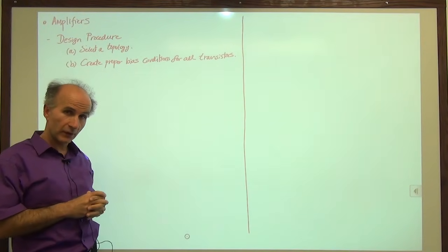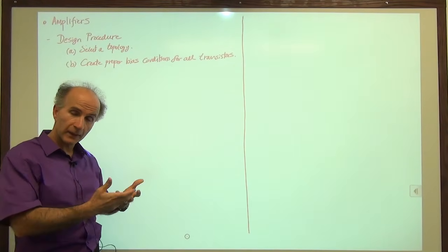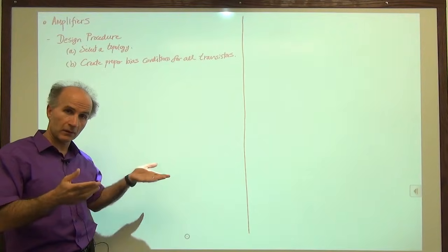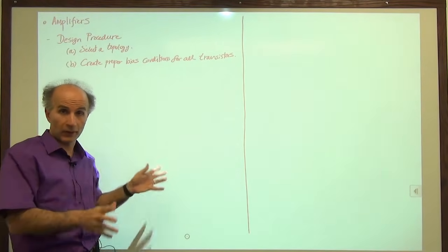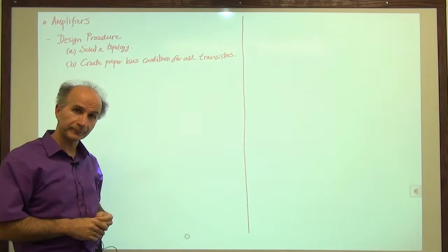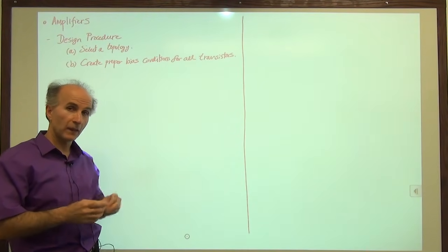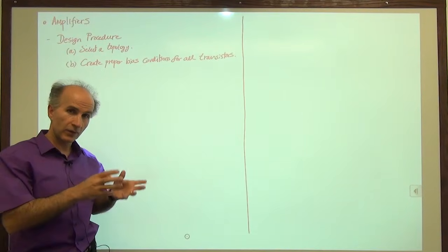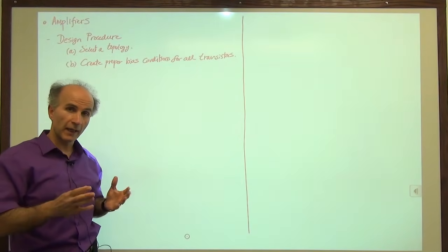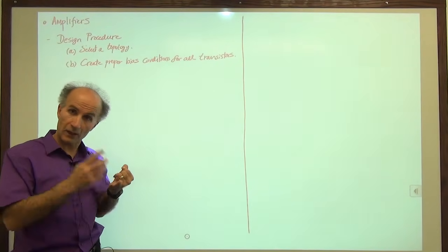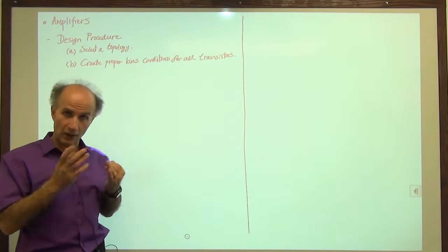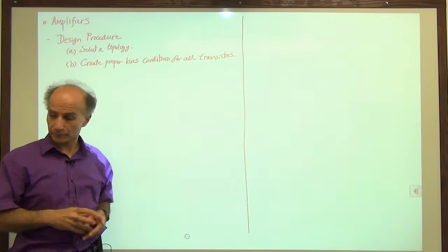Its transconductance is 0. When the signal comes in, the transistor is dead. The signal sees essentially an open circuit. There's no amplification. So we need to bias each transistor, meaning that without any signals coming in, each transistor must be alive and well. It has to have a certain constant collector current, a certain constant base-emitter voltage, and so on.